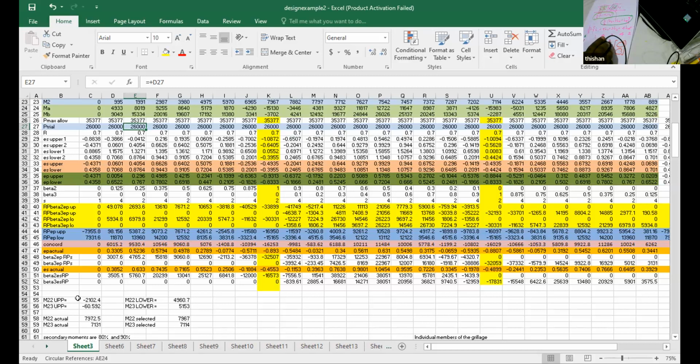Very quickly, you can find a set of loads that will generate a bending moment diagram using SAP 2000 with a little bit of trial and error. Right? With a little bit of trial and error, it will take about half an hour for you to fit a bending moment diagram, because there are plenty of solutions that can be fitted.